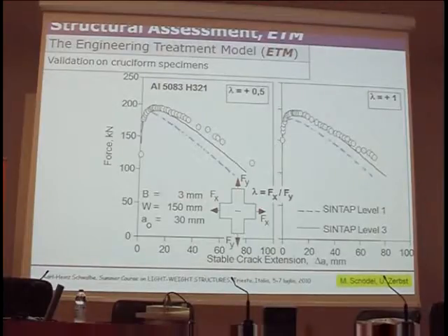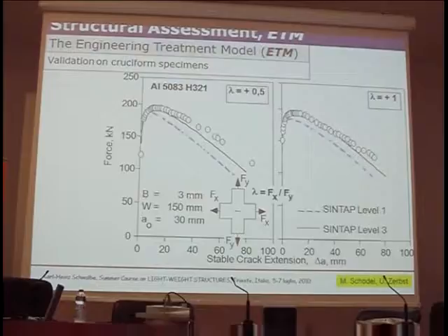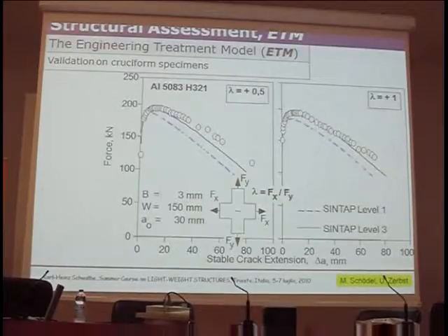Here we had tests, biaxial tests with different biaxial ratios. Here it's fully biaxial in the sense that both forces here are the same, and you see it's a relatively thin section, and with these dimensions here. And in our lab we have a 3D test machine. You can apply biaxial loads, plus we have a second set of actuators, so the machine has 6 actuators, which was specially designed for us. So we were not able to buy it from stock, off the shelf.